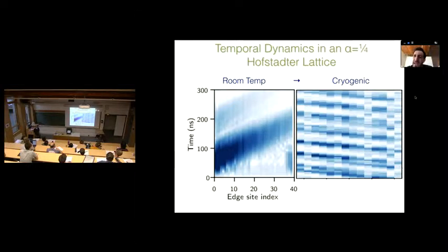And yes, in retrospect, there are some really neat sum rules that you can use to extract your coupling strength, and we can talk about that later if you'd like. Basically, if you measure the strength of the reflection and integrate the complex reflection over all frequencies, that gives you your coupling strength.